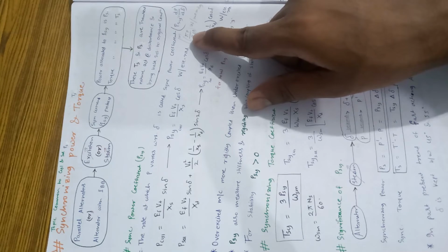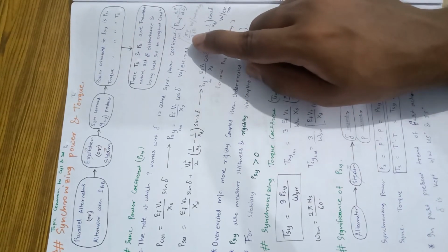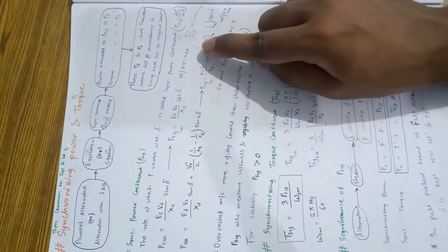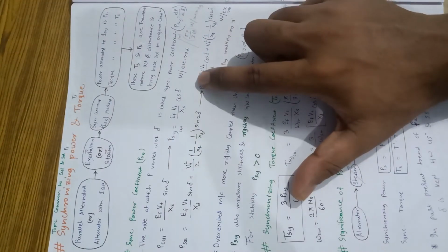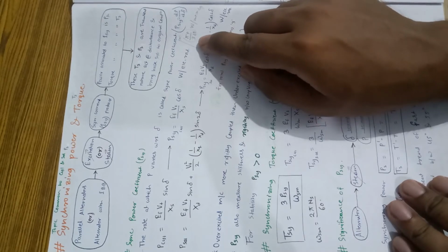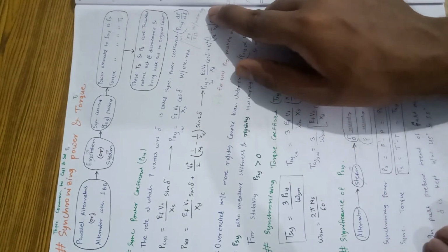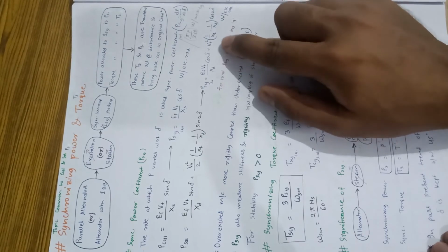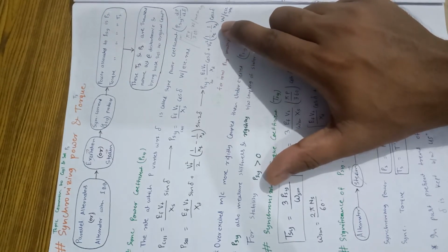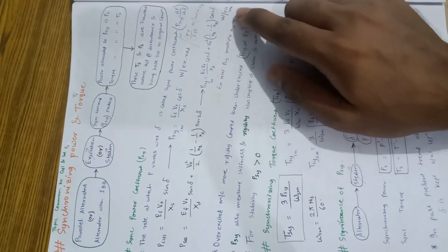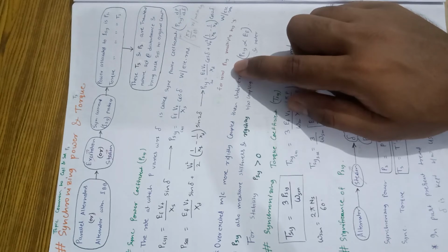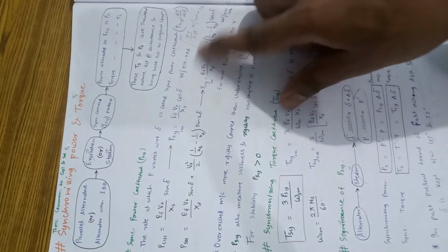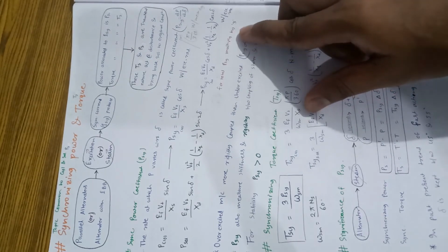How does it become pi P by 360? We know that theta electrical is P by 2 times theta mechanical, and to convert from radian to degree we multiply by pi by 180. So it becomes pi P by 360 watt per mechanical degree. After doing the derivation for the salient type, we easily get Ef Vt by Xd cos delta plus Vt square (1 upon Xq minus 1 upon Xd) cos 2 delta, in watt per electrical radian. For the total synchronizing power coefficient, multiply by 3, because these are per phase values. So for total Psy we multiply it by 3.